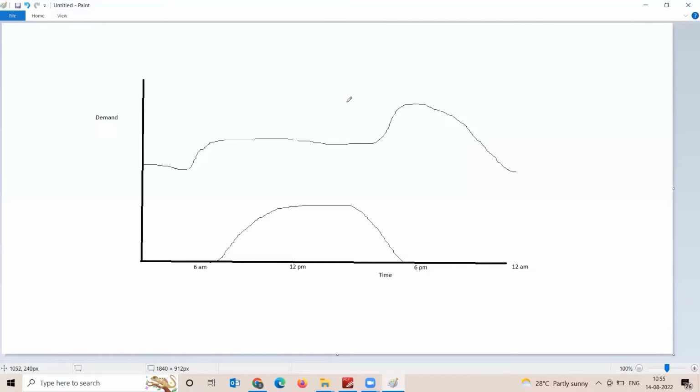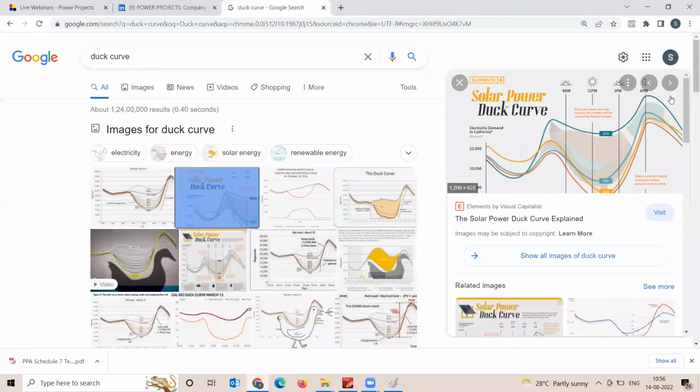But showing this diagram, what happens is, precisely at this hour, solar power is going down after 5-6 p.m., whereas at that moment your demand is increasing, if your country is predominantly domestic-load dependent, that is, driven by consumers in homes rather than industrial customers. It gives a message that the controllable generators, which have to balance generation and demand, have to ramp up at this time, to offset the decrease in solar and the increase in demand. And that's where you get what you have seen as a duck curve, right?